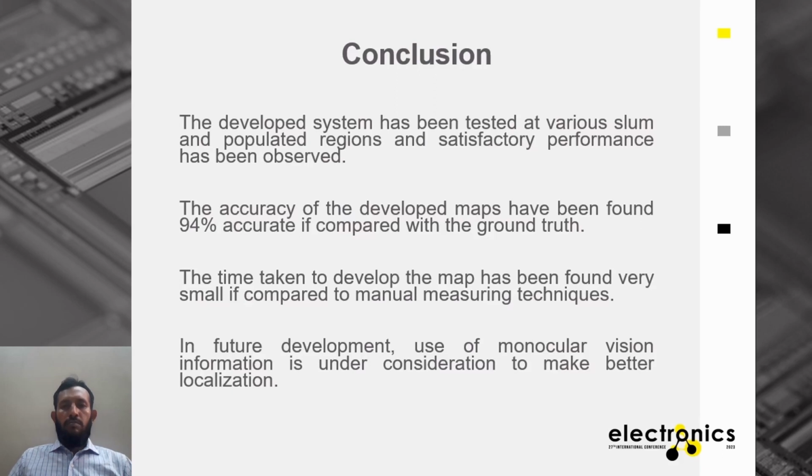But there are also some deficiencies which we are facing right now. For example, the stereo vision is always losing some common features, and we are not finding any possible poses from this calculation. So we are still working on this problem, and now we are trying to use the monocular vision information in 3 directions, as I explained earlier, that we have a front camera, and right and left cameras, to get better Z-axis localization information as compared to the erroneous information from the stereo camera.